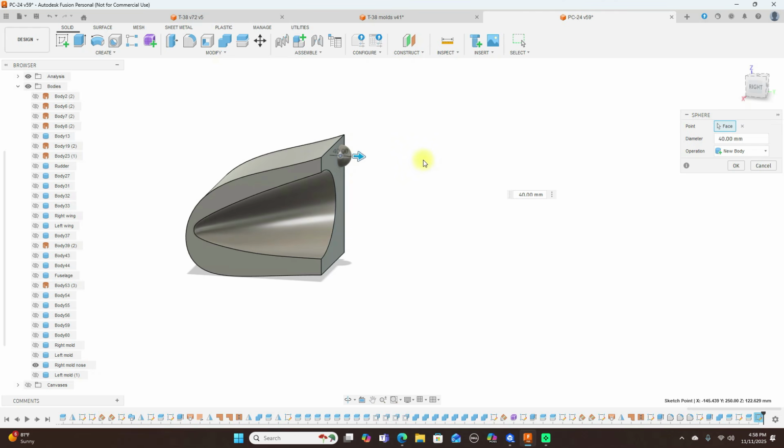But I always found that when joining the two parts, the hole over here is always too small, so this won't fit properly down into it. So I stopped doing alignment pins like this. So let's go ahead and cancel that.